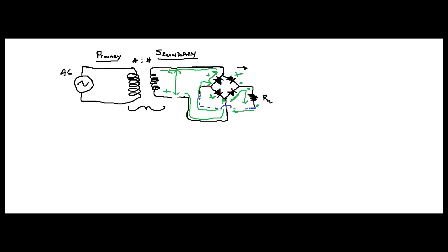And again, as you can see, two diodes are on. This is on here, on, and this is on over here. And these two here and here are off. And so you can say again that VP out equals your VP secondary minus 1.4 volts. That is how a bridge rectifier works.